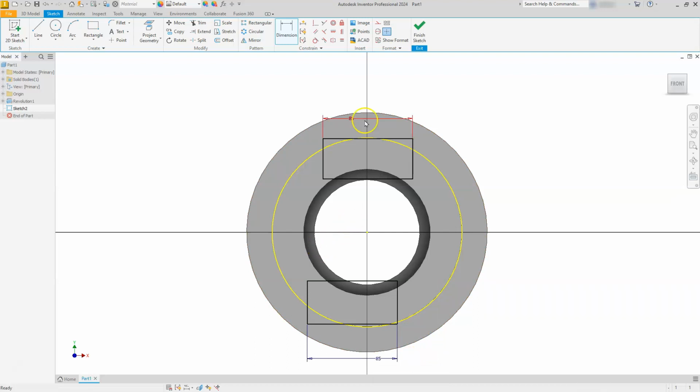Right? Let's keep these two in line with each other so that way I can do a little bit less selecting of things. So I'm going to use the collinear constraint. Select this line to this line. Alright, let's go ahead and add a dimension on it. We have a dimension that goes from this center to this edge. Once I come and place the dimension, I can select this 85 dimension and divide it by 2.